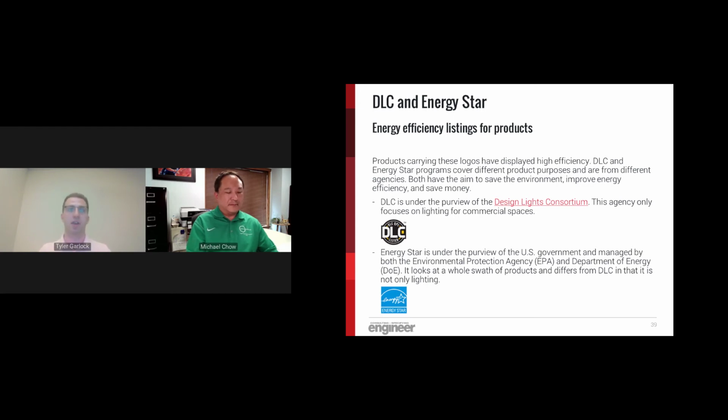Another key thing to really pay attention to is Energy Star and DLC really don't overlap. DLC does not list downlights. So if you have a project that says we have to have DLC, you're going to want to have that conversation with your architect or owner or whomever is requiring that, to really ensure that they understand that if they have to be DLC listed, you're adding money to your project, because linears are more expensive if that's your solution for not having downlights.